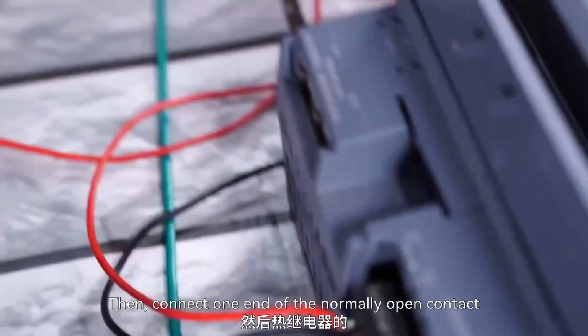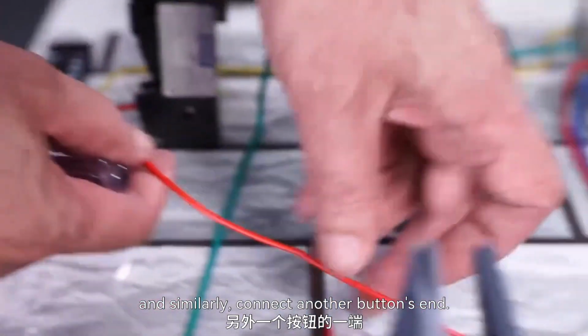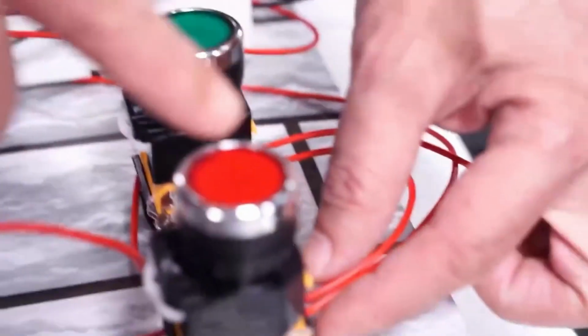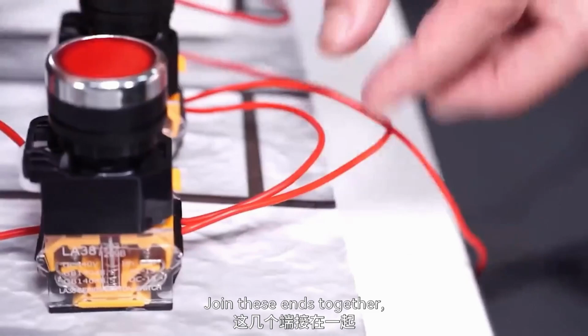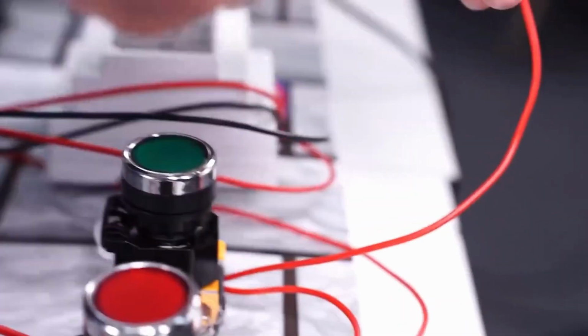Then, connect one end of the normally open contact of the thermal relay and one end of a button, and similarly, connect another button's end. Join these ends together, and connect the other ends to the common positive power supply L+.